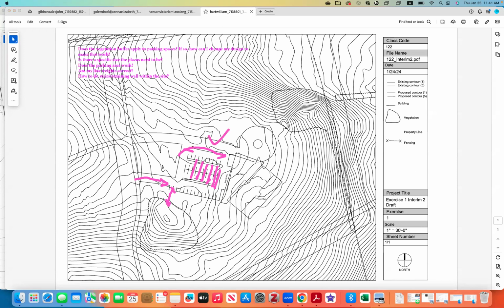If you don't have a separate entrance, if you want to get rid of this, the connection can come from here, okay? And the way you are doing it is correct. It aligns with the driving aisle inside the parking lot, all right? And in that case, close this off as well, having only one entrance. Because this is not a huge parking lot, one major entrance would be sufficient.